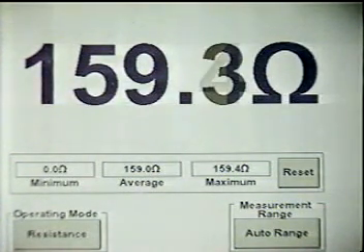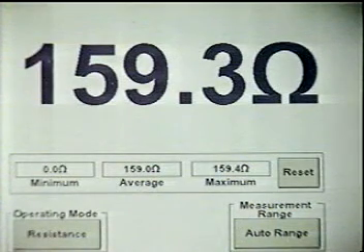But remember the limitations of a digital ohmmeter. We're only applying 0.5 volts into the circuitry of the pickup coil, and the spec for Toyota gives us, we're right in the middle of that spec. So remember, ohmic checks of pickup coils do not pinpoint weak magnets or too much of an air gap, so just because it passes the ohmmeter test does not mean the pickup coil is good. If you recall, we dynamically tested with a lab scope to prove to you that peak-to-peak voltage was less than 1 volt.